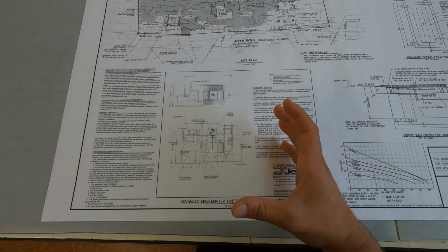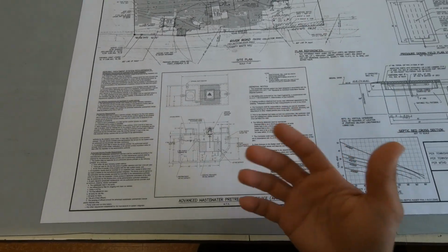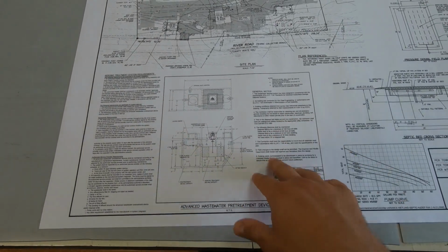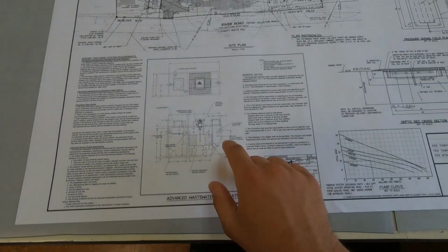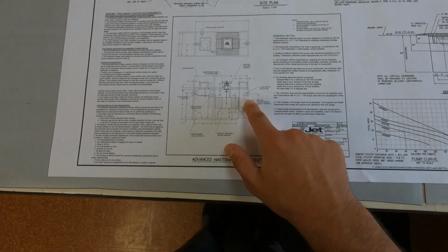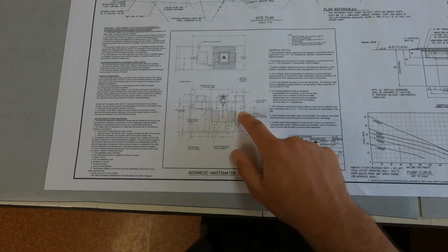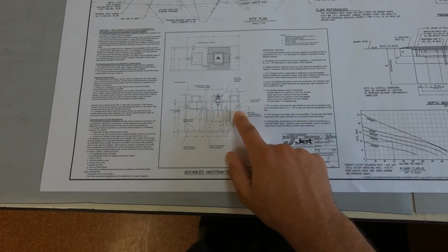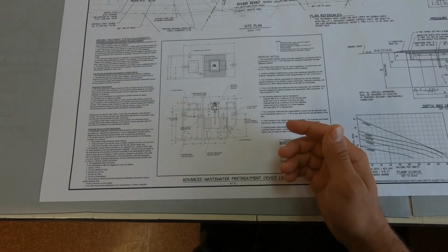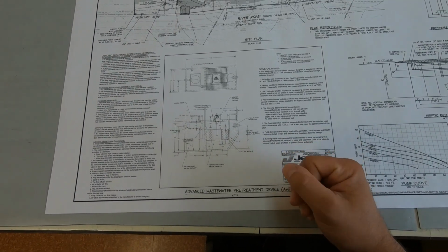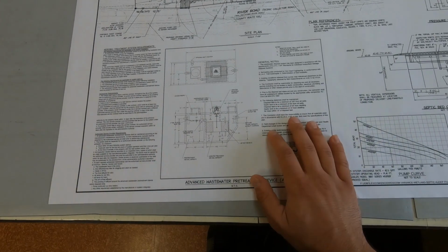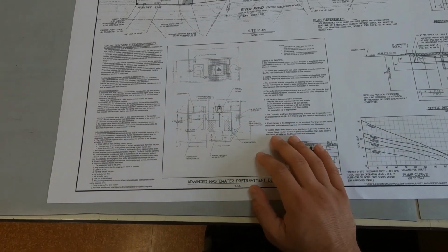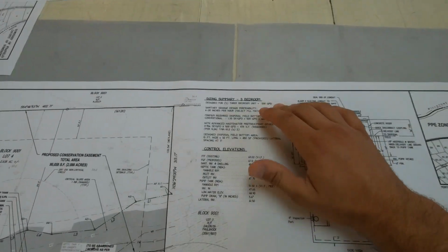There's usually this blue cylinder structure that gets put on the outlet T, which you can see here for the advanced treatment. There's an effluent filter that gets put in there. That's kind of a new requirement, I believe, for the state of New Jersey. It may not be required if you're not working in the state of New Jersey, but that's something that I try to verify.